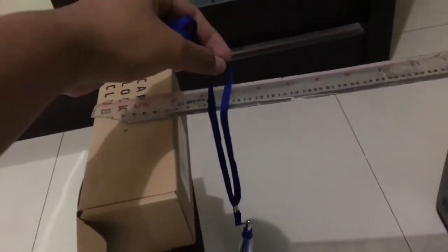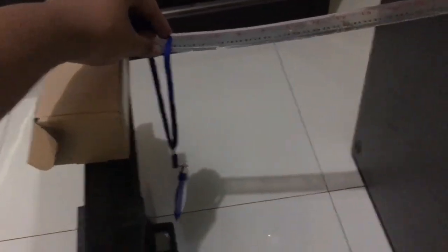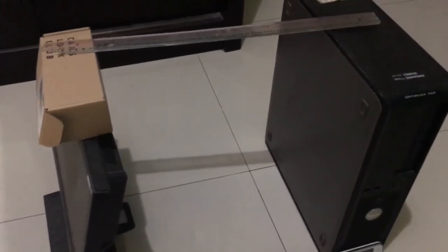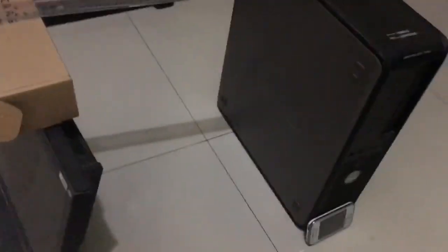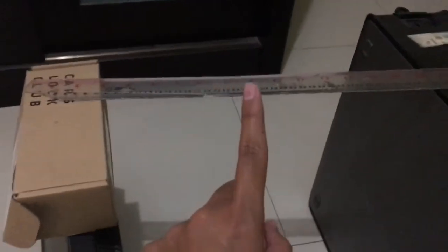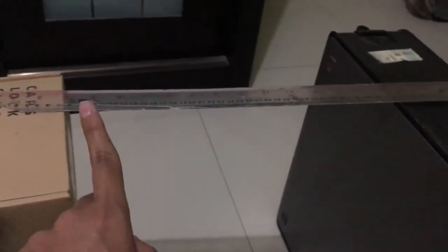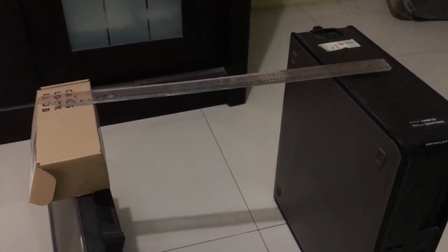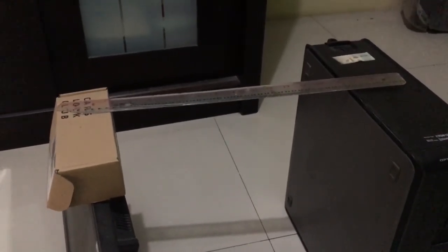We put the mass in here on the arm and we set the digital force reading to 0 Newton. And one another thing, before we put the mass, we need to first measure the length between this point and this point, and from this point to this point. After we measure the length, we see the digital force reading, and then the result we can multiply it and we can find the bending moment. That's all for the bending moment experiment. I'm sorry for the mistake. Thank you.